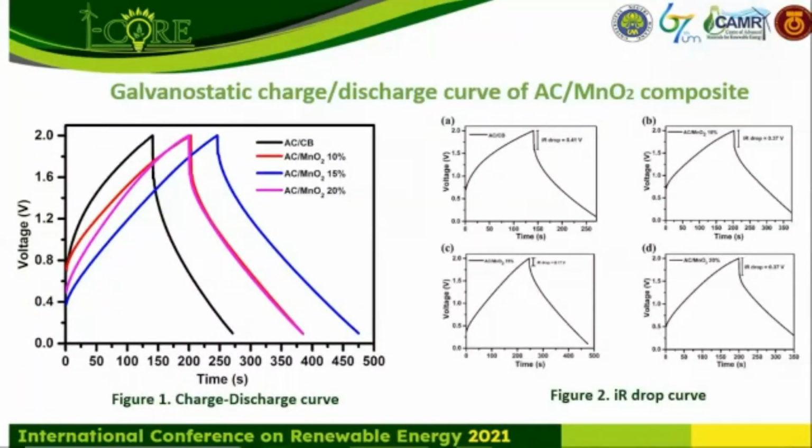The charge-discharge technique is widely used in capacitor characterization. In this study, we will only focus on charging and discharging at a constant current. In the charging process shown in the figure below, the supercapacitor is charged at a constant current with the voltage changing from the discharge state to the maximum operating voltage. This figure shows the charge-discharge curves using a 2-electrode test cell in which the 2 electrodes are identical, a symmetric cell.